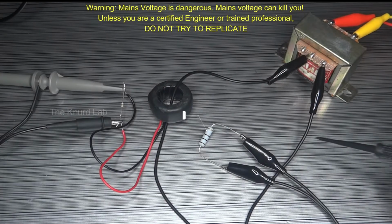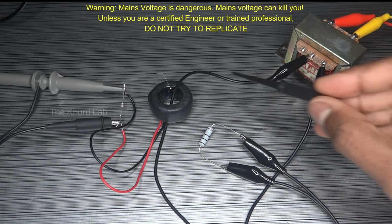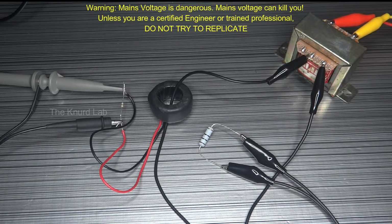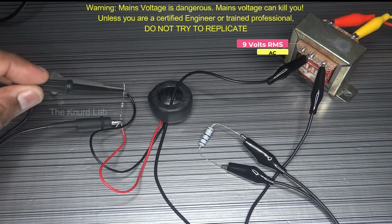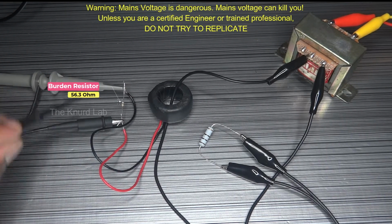A 10 ohm resistor connected across 9V AC supply forms a primary circuit. The current flowing through the primary is measured using a current transformer. A 56 ohm burden resistor is connected across the secondary of the current transformer. An oscilloscope probe is connected across the burden resistor to visualize the voltage waveform. After making sure the connections are safe, let's power up the circuit and observe the primary and secondary voltages.